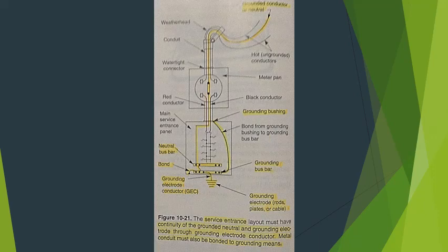Service grounding. Grounding the service entrance is vital to the safety of the entire electrical system. Careful attention should be given to this section to ensure a thorough understanding of the procedures involved. In addition, you should study all sections of Article 250 of the NEC before undertaking any electrical installation. Grounding the service entrance involves connecting the neutral or white service conductor with earth.